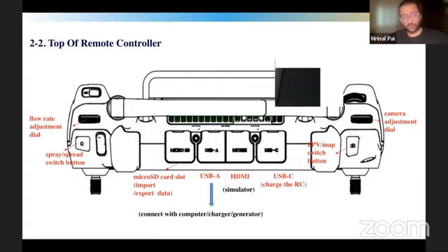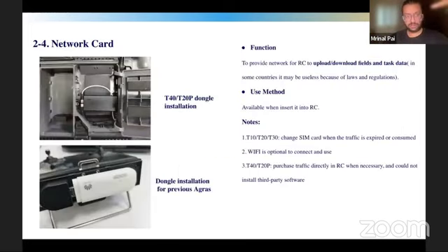Yeah, so you can adjust the flow rates, for example. And these drones also come with cameras, right? There are also a front camera and a backward camera for the operators. Some variants have a multispectral camera as well. So in case you want high precision farming, where you do a health assessment of the crops and spray only where damage is assessed, the same drone can also come equipped with a multispectral camera, all of which can be controlled with the remote controller.